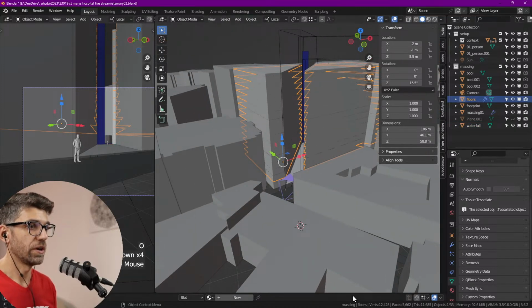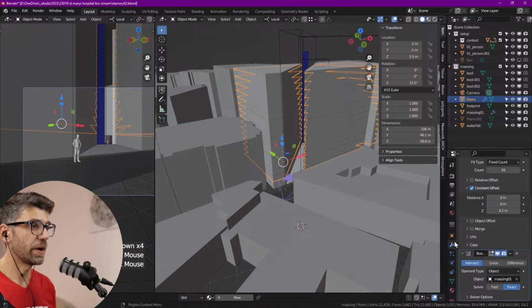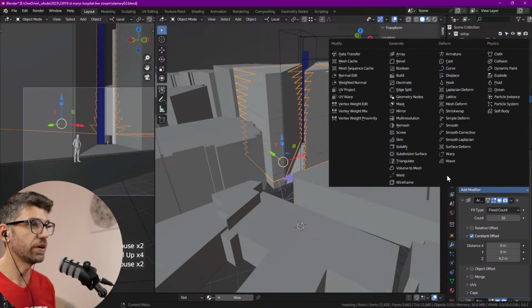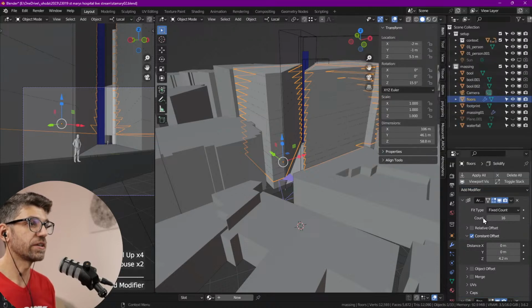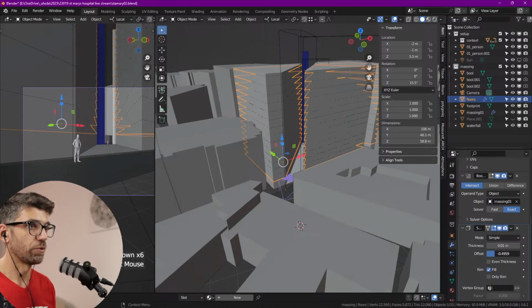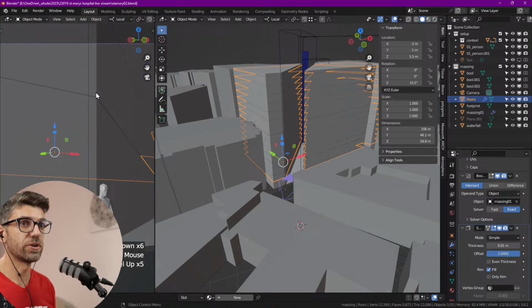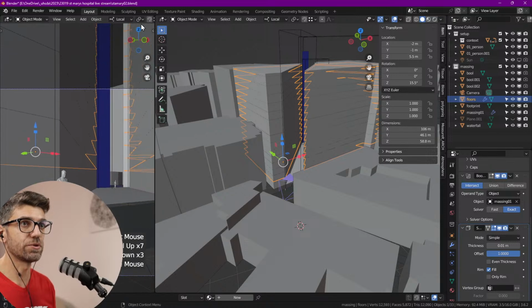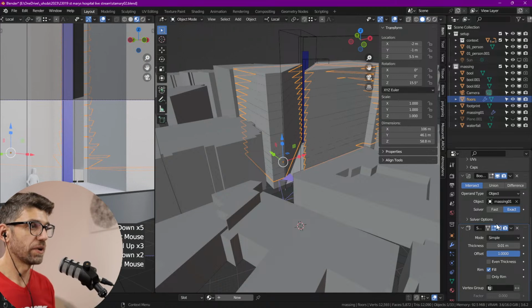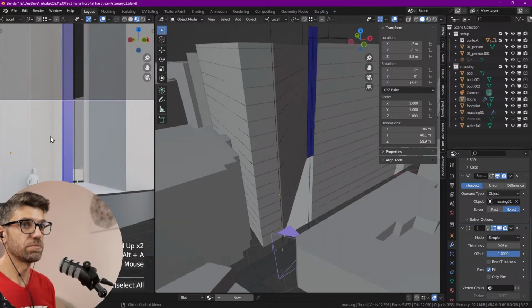Floors over here. And we can slightly grow them by adding a solidify modifier just for the massing, the initial part. So we understand their actual size. And we want that to go on the +1. Why do I want to see that? Because now in this view, we should be able to see that. And let's turn on material preview, so we have a slightly better understanding. And I'll grow these a little bit more. There you go. Now they should be visible.